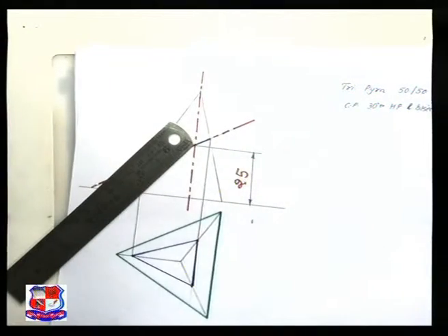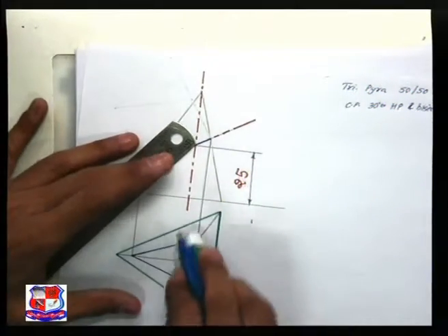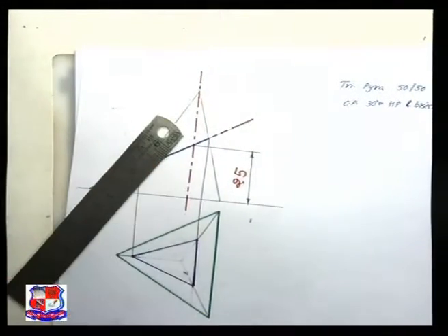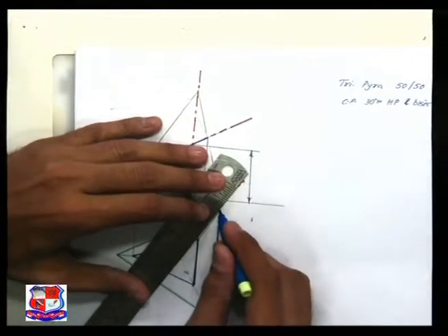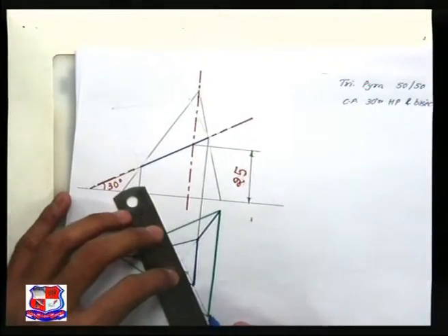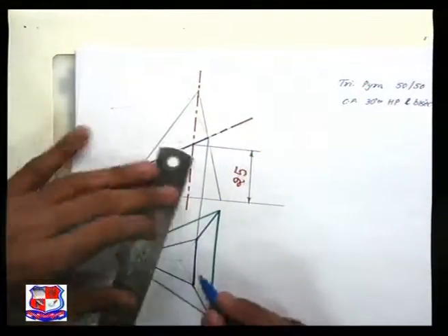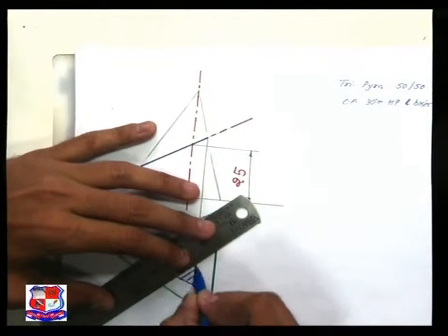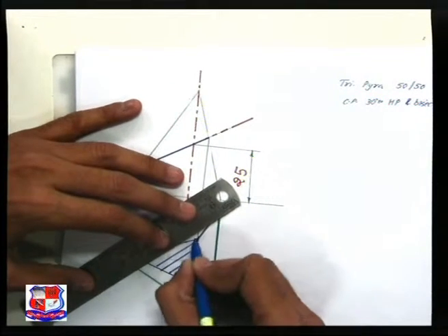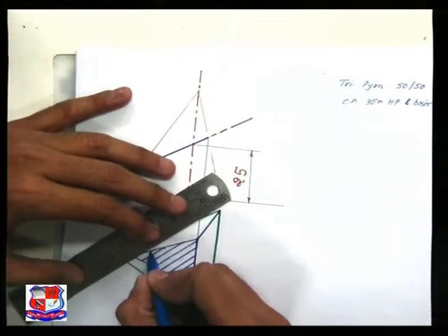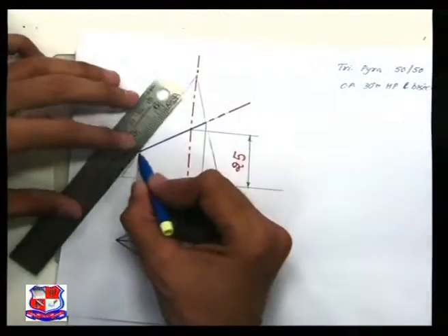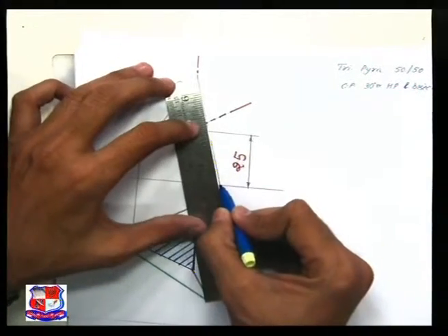Here this internal portion is removed, so you can erase these slant edges over here, as now it is a flat portion, and here this would be visible. So you can draw straight lines up to this end only, right? And as it's a sectional top view, you have to draw section lines which make an angle of 45 degrees with XY line, and all these lines are equidistant. So this is the sectional top view, and in the front view this is the remaining portion with us.